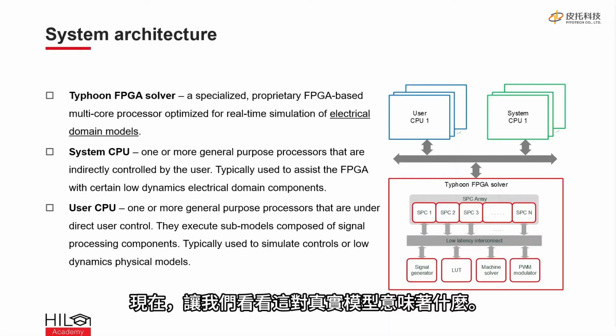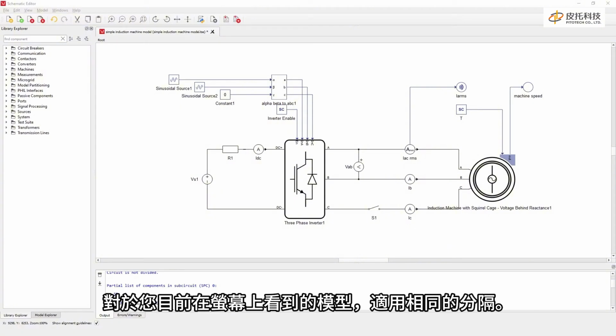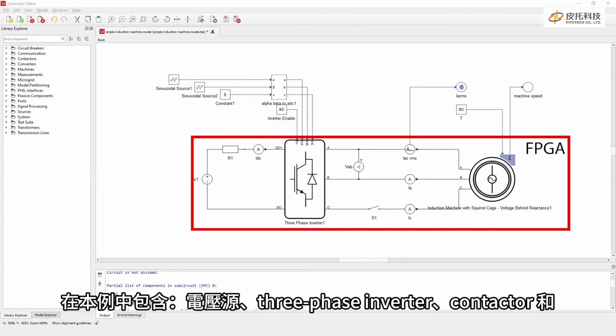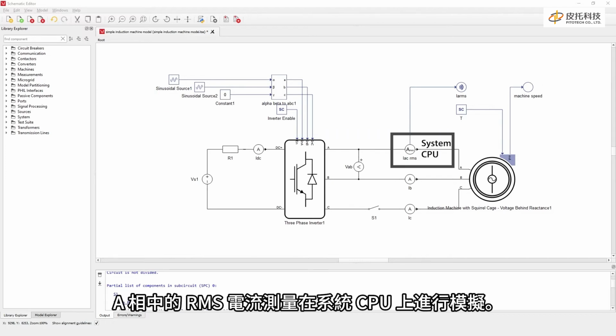Now, let's see what this means for a real model. For the model you currently see on the screen, the same separation applies. The electrical part of the model is simulated by the FPGA circuit solver, which in this case includes the voltage source, the three-phase inverter, the contactor, and the electrical machine. Control of the inverter, which is comprised of the sinusoidal sources, the constant source, and the alpha beta to ABC component, are simulated on the user CPU. The RMS current measurement in phase A is simulated on the system CPU.